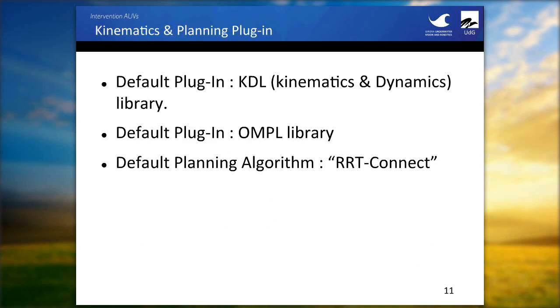For the kinematics and planning plugins, we use only the default plugins, the KDL for the kinematics and OMPL with RRT Connect for the planning.